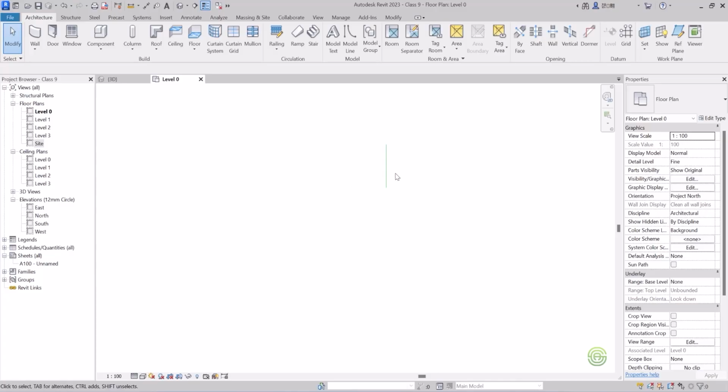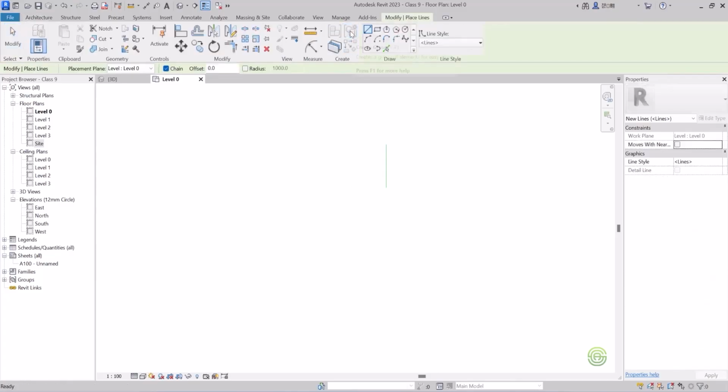So now the slope ratio is like, if you just want to reach 1 meter height, then the distance that you travel depends upon the slope ratio. If you are traveling 2 meters to reach 1 meter height, that means it is 1:2.